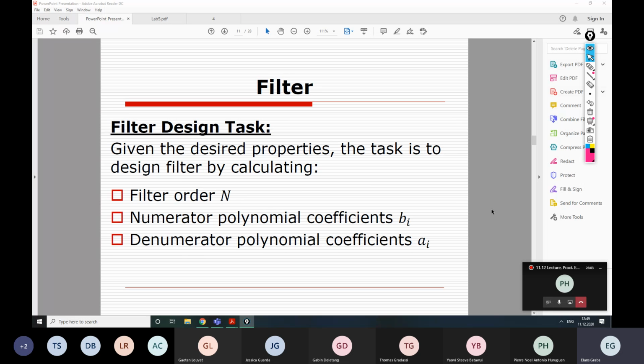So, for example, we have some properties like what cutoff frequency do we need, F0, right? What level of the signal we must provide at some control frequency, and what's the minimum allowed value in the passband, so that would be H minimum for our filter.